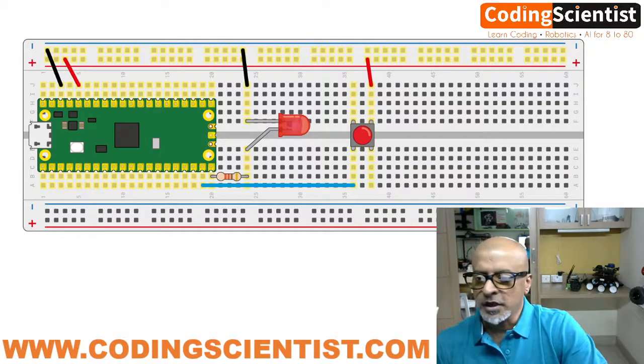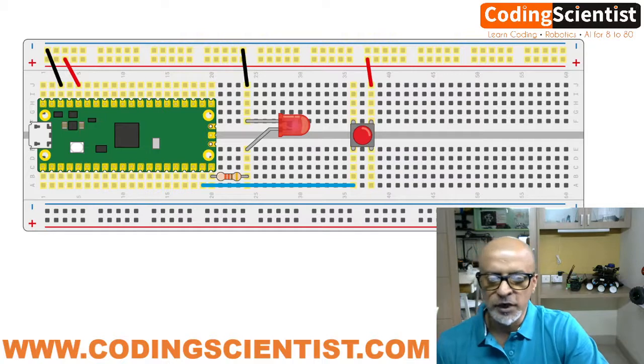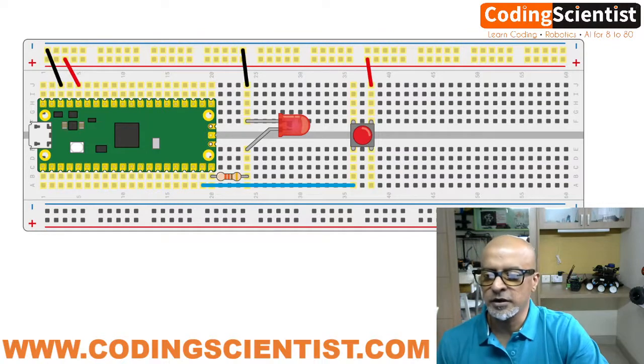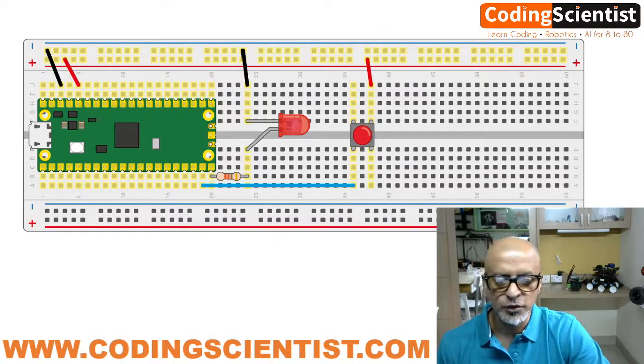And then we are bringing the entire thing into the loop, while True. If the button.value is true, then what happens? The LED has to toggle. All right, it's toggling, and then time.sleep. All right, looks okay. Let me just try to run it and see.